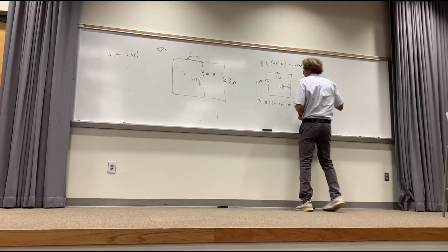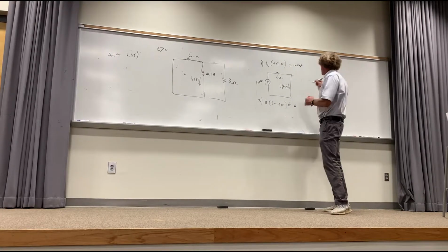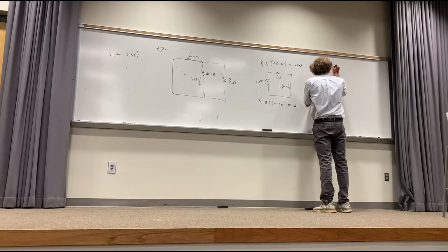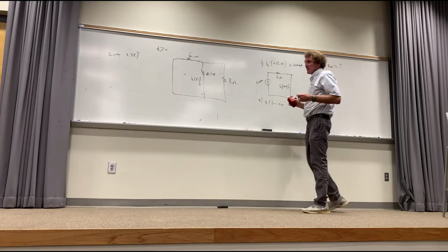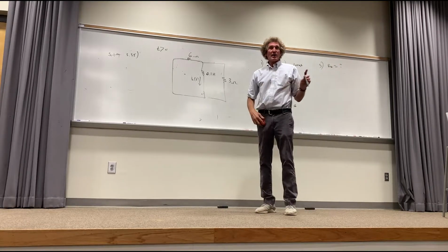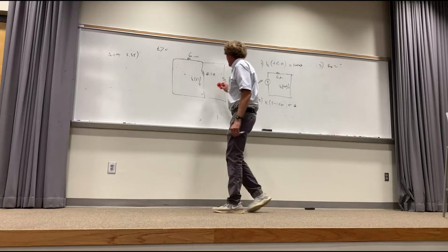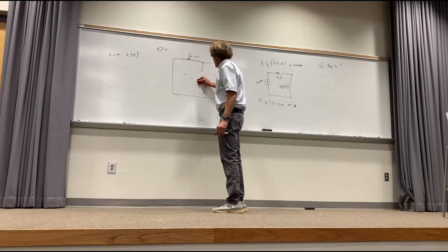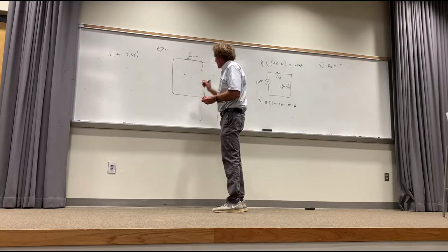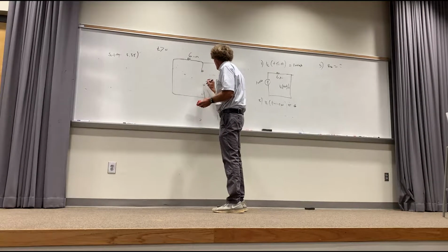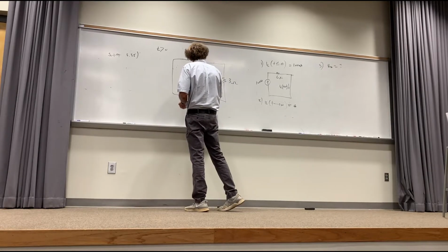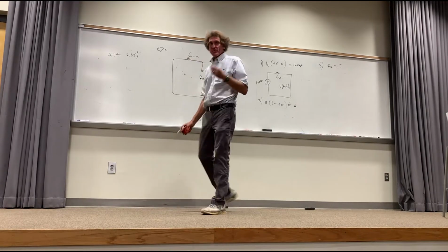Now the third thing, I need my R Thevenin, right? Correct, class? Well, how do I get R Thevenin? After the switch changes state, I can erase whatever it is. It's the same if it was a capacitor, right? And I look at the Thevenin resistance across these 2 points. I will slow down because I've been asked to.